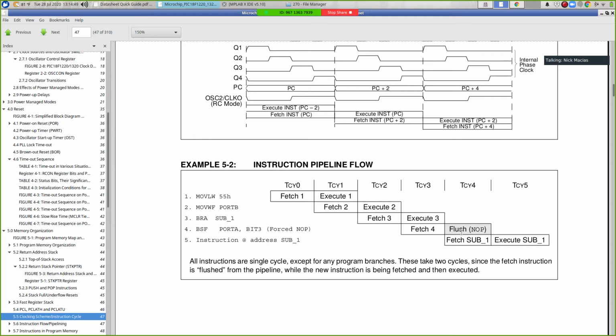But on a sophisticated ARM processor with a 13-stage pipeline, we're going to see a 13x drop in speed for the next 12 instructions, while our empty pipeline, our pipeline that's been flushed, is slowly getting filled up again. These branches are brutal. And a lot of work has gone into dealing with this problem.